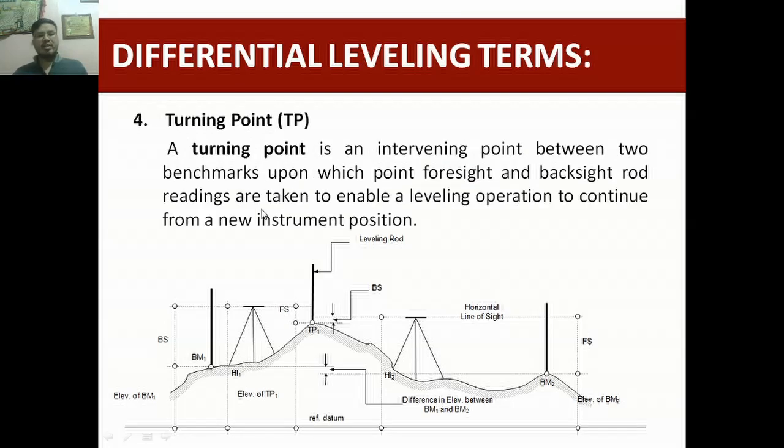Next is turning point. A turning point is an intervening point between two benchmarks, like this in our illustration. Maybe you set up at benchmark 1, and benchmark 2 is far away and not visible, so you use an intermediate point, which is what we call a turning point.